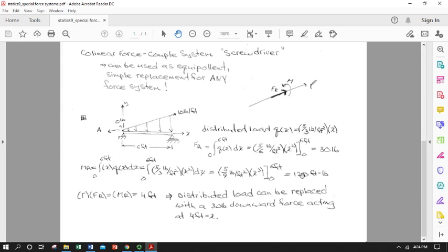So in order to achieve 120 foot-pounds of torque or moment from a 30-pound load, it better be at 4 feet from the turning point, from the point around which I'm calculating the moment. So I'm going to have to put F sub r right out here at 4 feet. And this is the moment of the sum is equal to the integrated sum of the moments.